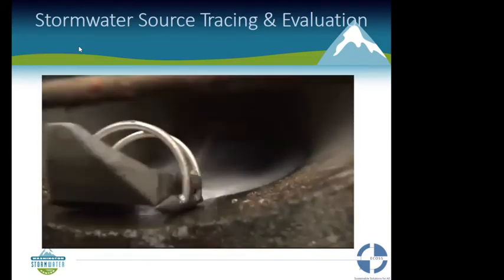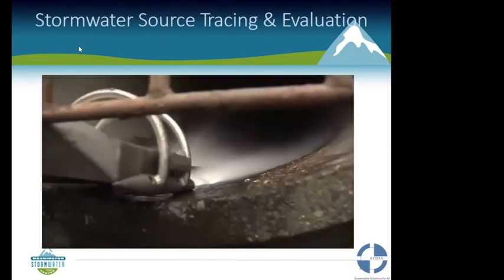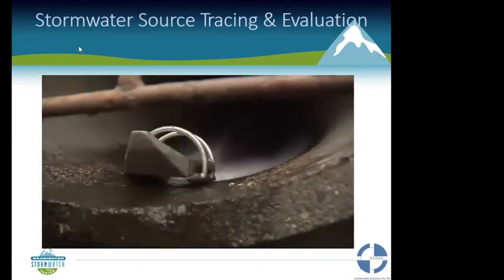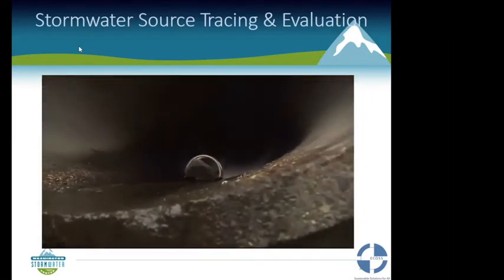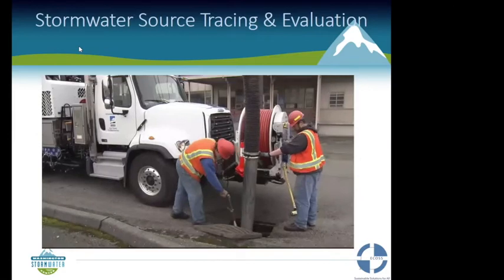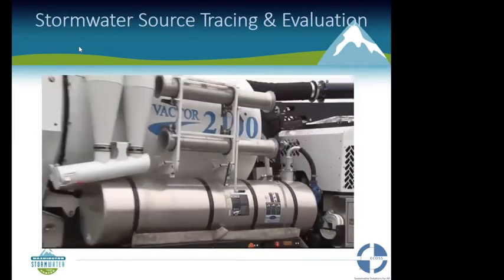We actually use a jetter hose on the end of a cleaning head, and it uses high pressure water and brings the material down to a central location where that oversized shop vac is able to pick the material up out of the line.